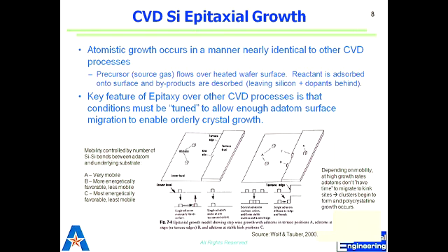This growth is different from nucleation growth, where with poly or amorphous material, they grow differently. They have nucleation sites where there are small islands, and then they grow and catch each other and form a film. In the case of epi, it is a terrace which is following the bottom substrate and growing.